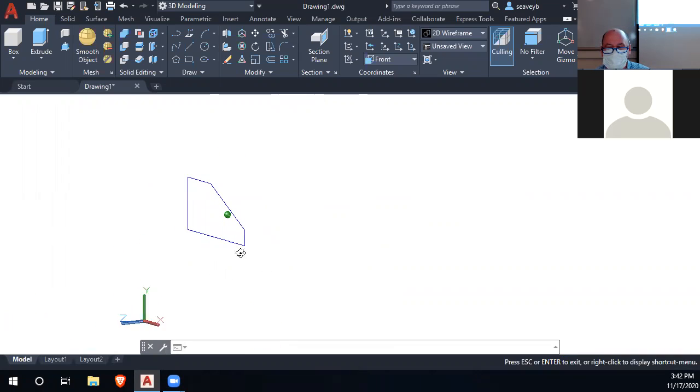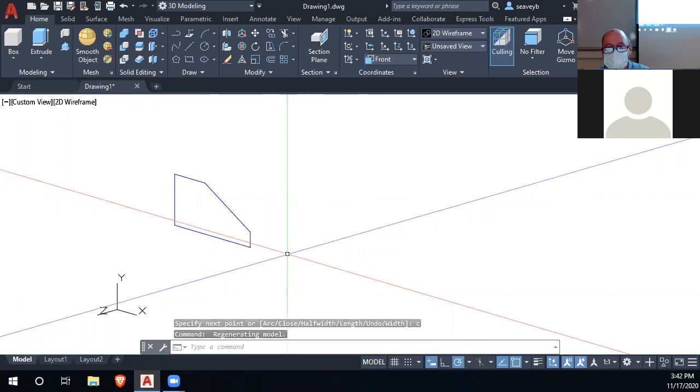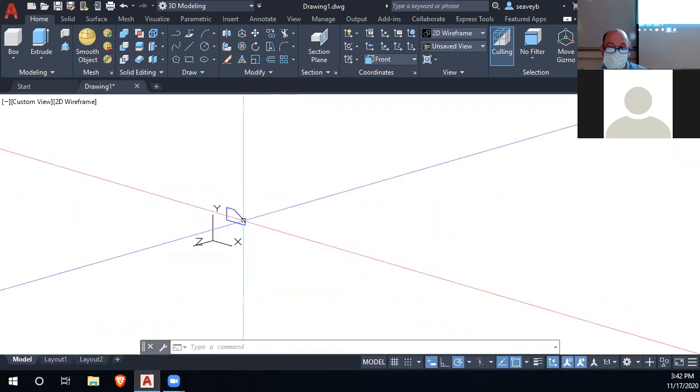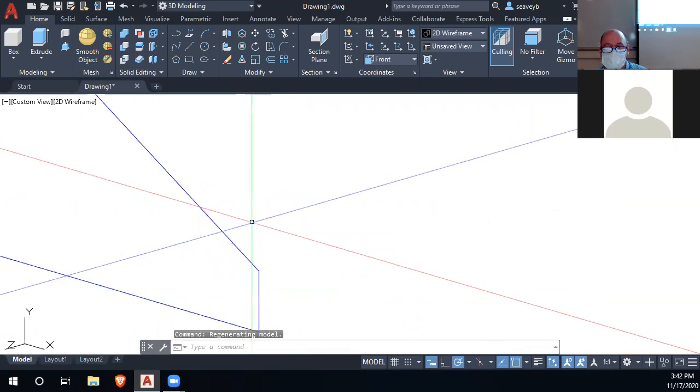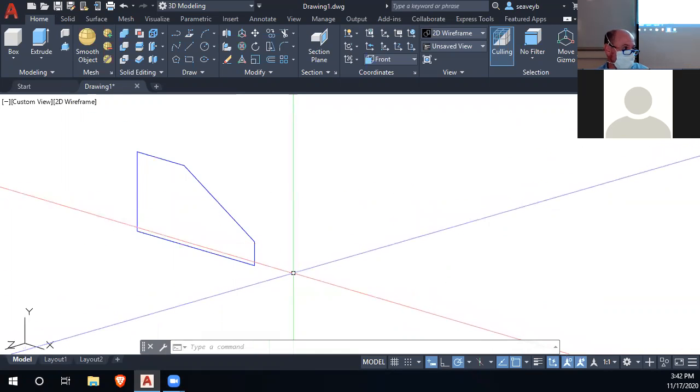Yeah, hold that shift key down while you pan. Before you pan and while you pan. How do you pan? Hold this button down. The middle mouse wheel is a mouse button also, so you press it and hold it. Don't roll it, because rolling zooms. Hold the shift first and then pan.